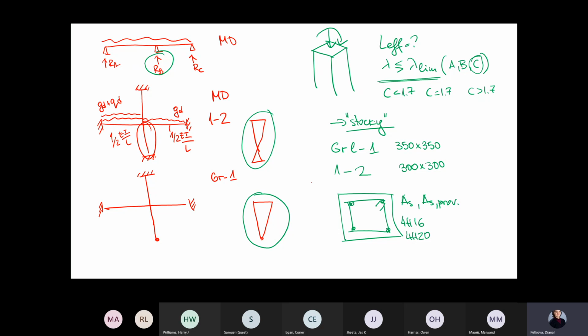Of course, if you are working on a ground floor column, this column will come from the foundation. Okay, so let's say we have a pad foundation. If you have some reinforcement here on the bottom, you will have some starter bars. And you will have now the new bars from the new analysis. I've skipped the kicker here, but you'll see the drawings. And then of course you'll continue to the top.